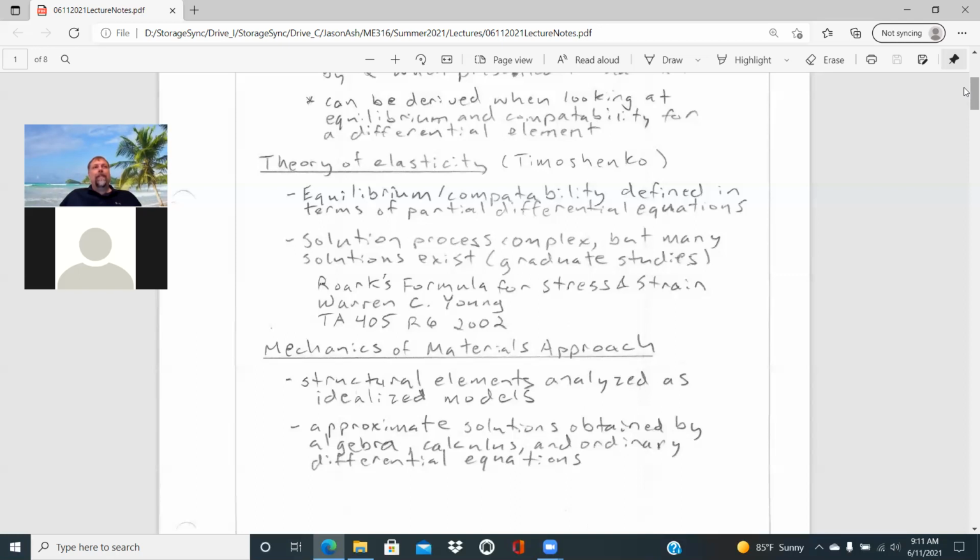That's my biggest concern always when you undertake a finite element analysis, is that it is easy to make a model and put loading on it, boundary conditions, and get nice numbers and figures out. But if you've put incorrect information in anywhere in that process, those numbers are not going to be accurate.